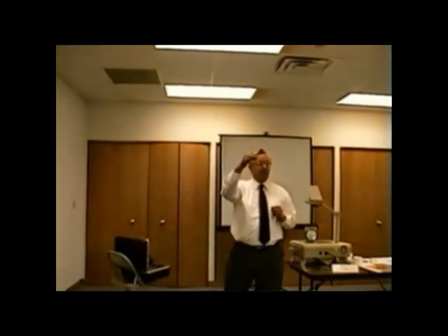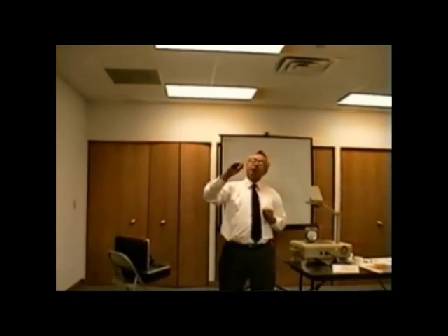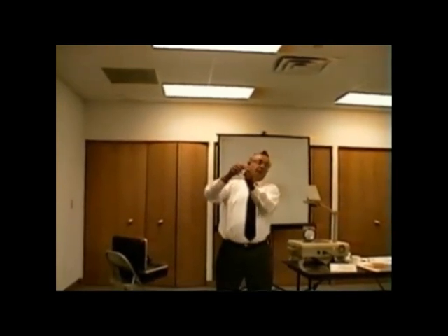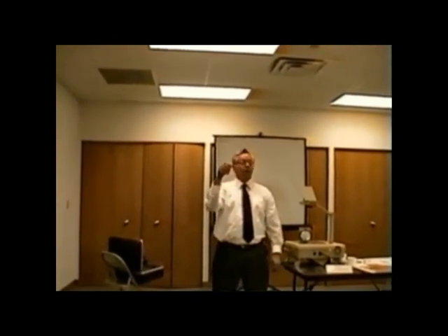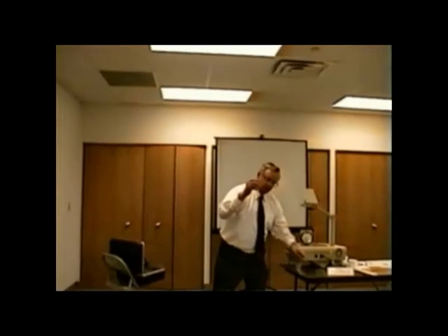Now you go to 5 classes, you get 5 different opinions about how to use this. I'm giving you the accurate one because I called Dwyer. I said some people say put it this way, some say put it this way, some say put it this way, and other people say this way. I said, what's the correct way? Because you're the one that makes it. They said this way, but I got to tell you, when I stick these things in ductwork and I get my reading, I turn it around and it hardly moves. But the point is, Dwyer says, let the air hit it this way. So now you understand. It goes under the coil, in the airstream. That's it.